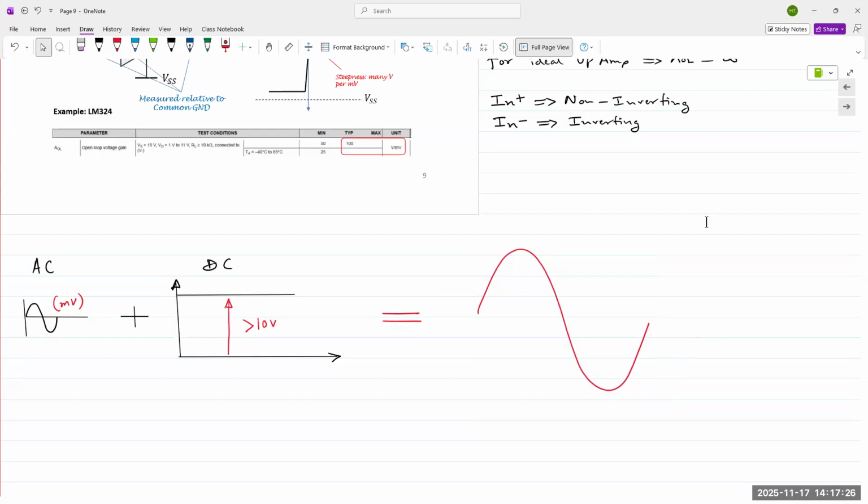As an example, let's say an amplifier has a gain of 100. If you feed it an input signal of 0.1 millivolts, what output do you expect to receive? 0.1 times 100. All right, forget 0.1 millivolts. Let's just say 0.1 volts, right? So what's the output voltage? 10 volts.